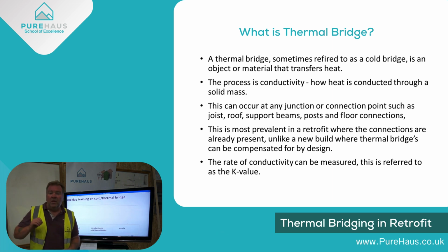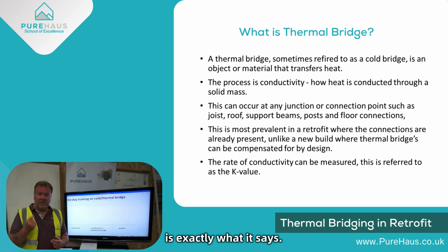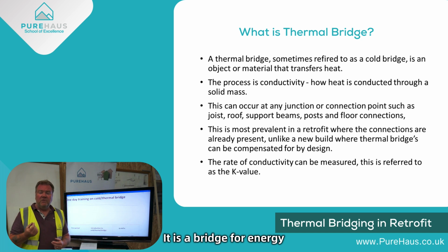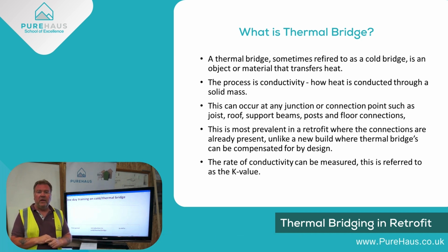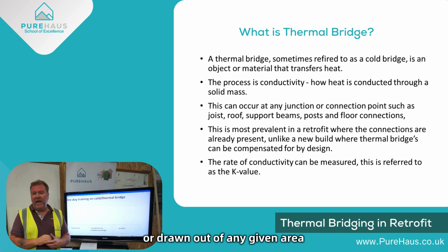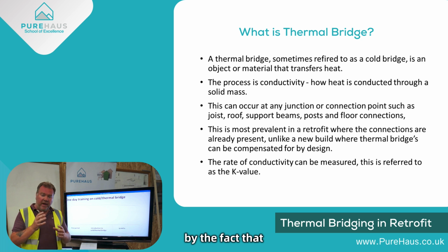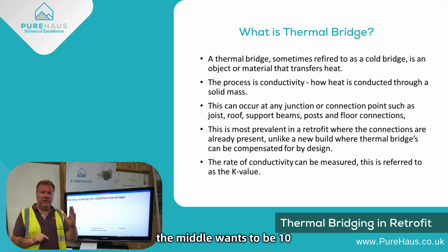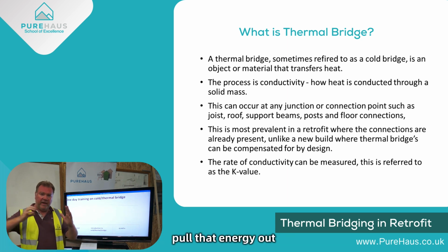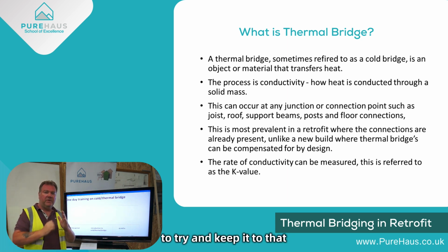So, thermal bridge is exactly what it says. It is a bridge for energy or heat to be drawn out of your building or drawn out of any given area by the fact that it will conduct heat. Because if it's 20 degrees there, 0 there, the middle wants to be 10, and it will pull that energy out to try and keep it to that point.